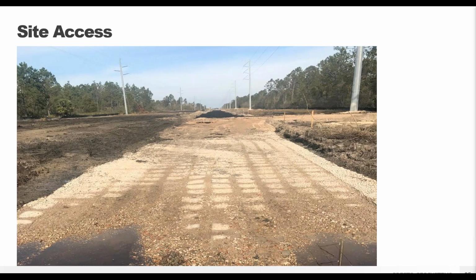So once those GeoWeb panels are actually filled in, both wheeled and tracked equipment can drive over the system. So even when the material is sand or that other low quality stone that you might have, which would normally be horrible to try and drive tracked equipment over, it's totally easy to use with the GeoWeb system. And again, you can see how the GeoWeb panels act as their own access road. Just keep filling up the cells in front of you. No need for those additional temporary.